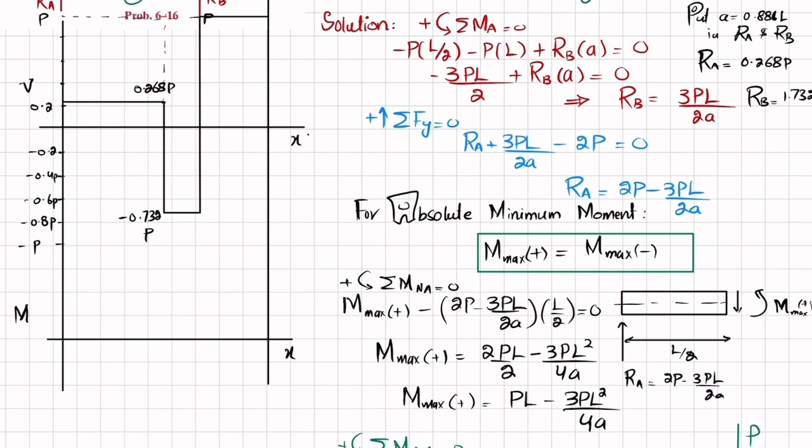So we'll plot this. Let this be 0.1 P into L, this is 0.2 P into L. And similarly minus 0.2 PL, minus 0.1 PL. So the first point is 0.134. At this point we have moment equal to 0. And if you project this, let this be the point 0.134 P into L. And you can see that shear force is a horizontal line, so the bending moment will be one degree higher and the slope will be increasing because this area is positive. So I will join this. So this is the first point.